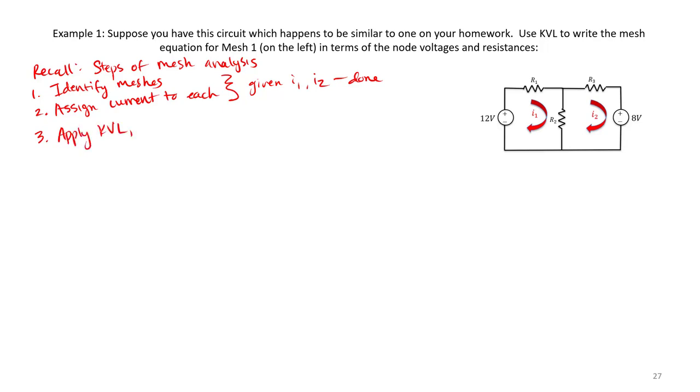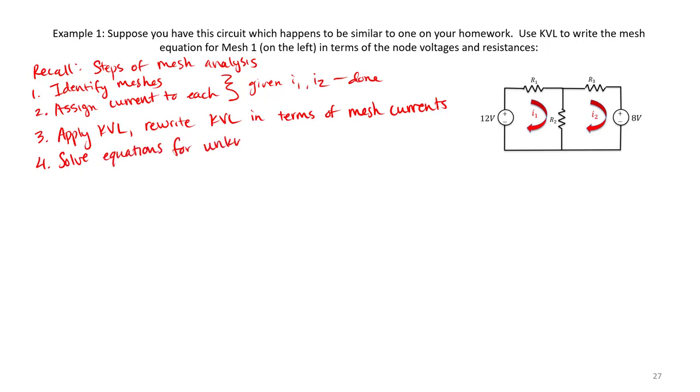So we write our Kirchhoff's voltage law equation and then rewrite it in terms of the mesh currents. And then finally, we would solve the equations for the unknown currents.